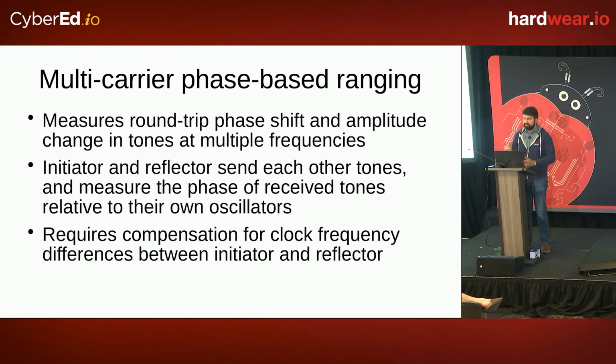One thing to note is that in real devices, the clocks will not be perfectly synchronized. There'll be small differences in the crystals and inaccuracies in there. So the spec handles that by having an additional mode called mode 0, where it measures the frequency offset between the 2 devices and then compensates for it in software afterwards.